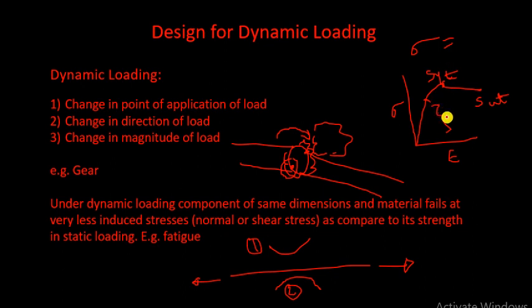So in this elastic limit, from this to this area, there is a very negligible deformation which is acceptable. That means under that deformation, the component will perform its function with an acceptable change in the dimension. So there will be no lesser efficiency, or there will be a permissible change in the dimension. So we can assume that this is a safe stress, or the safe zone, where we can apply forces up to this limit. After this there will be a plastic deformation.